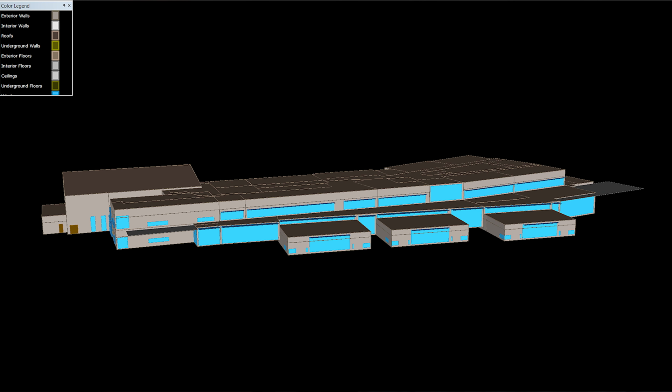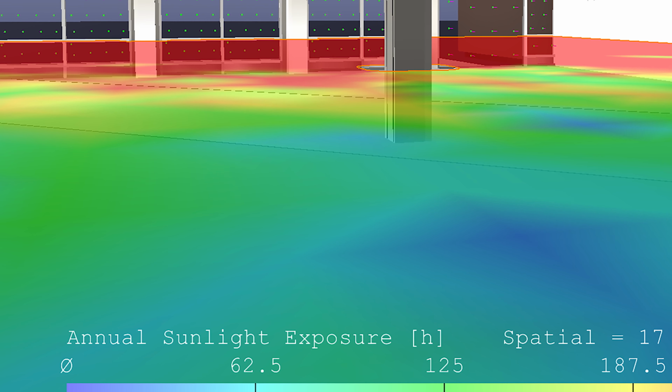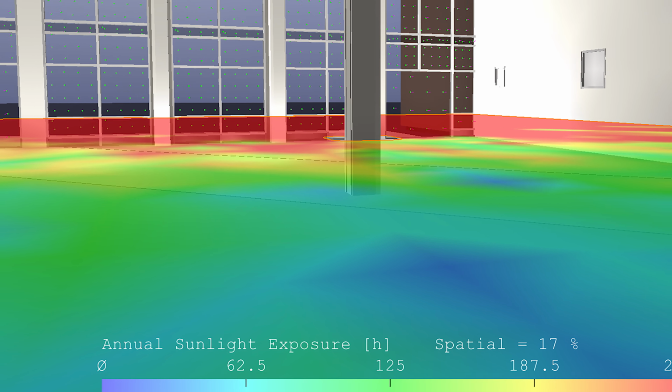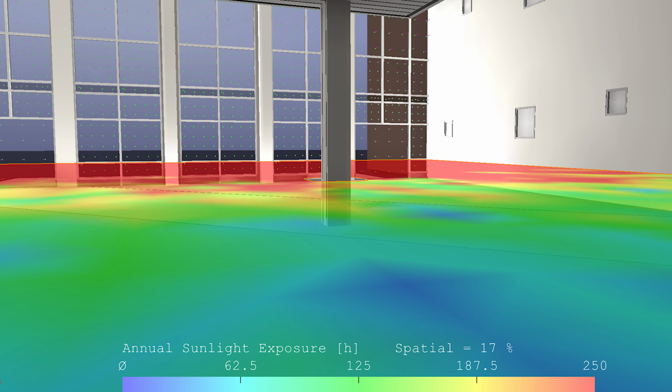Next, we want to improve the daylighting. So past projects have always over daylit classroom spaces. So new technology allows us to look at not only the solar daylighting autonomy of how much daylighting is evenly distributed throughout the space through the entire learning year, but also how to reduce annual sunlight exposure and eliminate the glare that could come into a space and really hinder the learning aspects. So we're achieving great performance-based metrics in annual sunlight exposure, but yet minimizing the annual sunlight that creates glare.